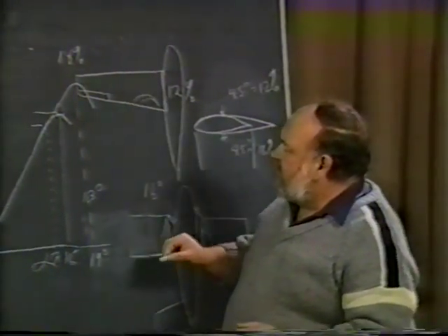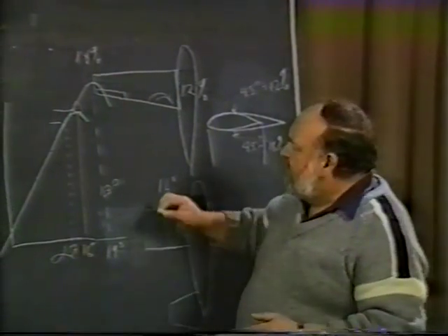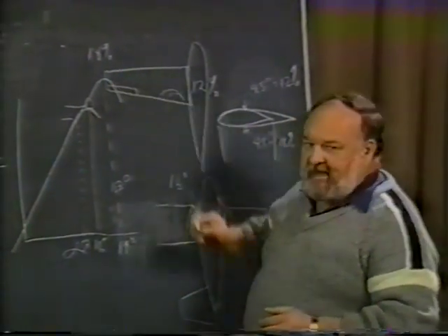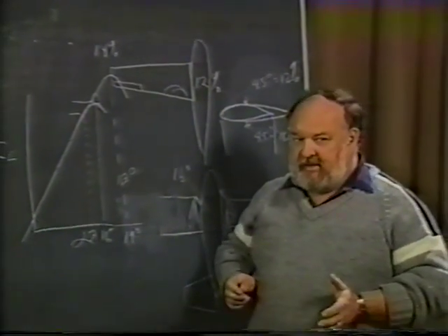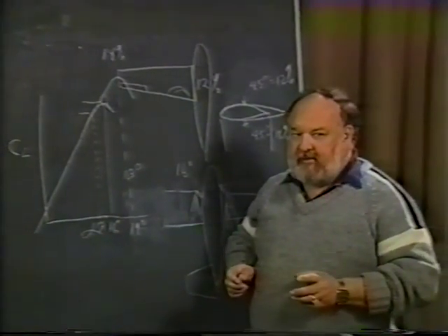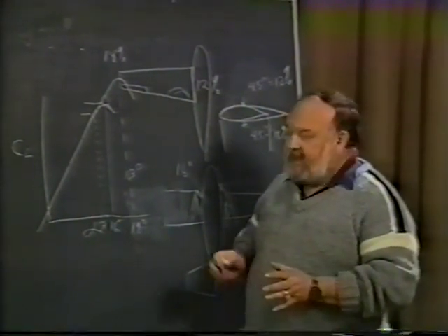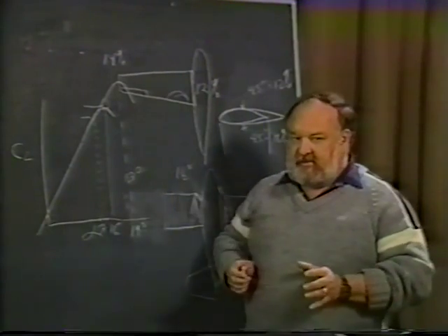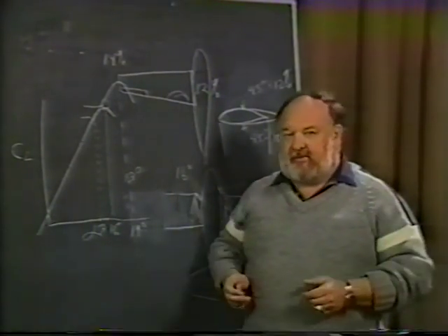As the aileron goes down, which is like a plane flap, the outboard section will not stall just because the aileron went down. This is one of the dangers you have to worry about if you do not have a good stall pattern and if your outboard section is relatively sensitive. A J3 Cub was a good example.